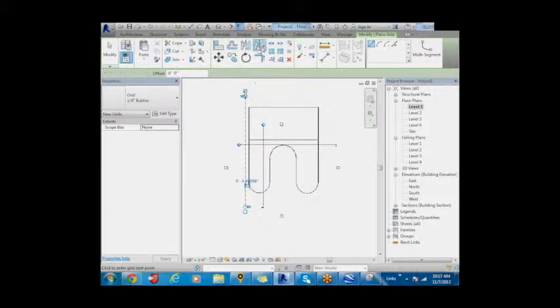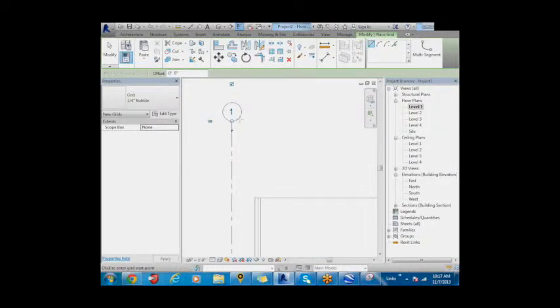For the grids, I could try to align them to the actual lines for the external walls and the other walls. But as with most things, remember how Glenn does it: it puts it right close to it and then you align it so it locks. That's what I'm going to be doing here. You also want to take note of the labels for the grids. Different places have different standards, but we typically have numbers on the vertical and letters on the horizontal. So you can identify columns and beams like column A1 or beam 1AB.